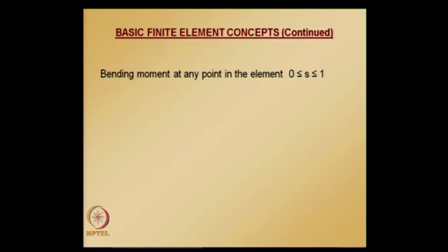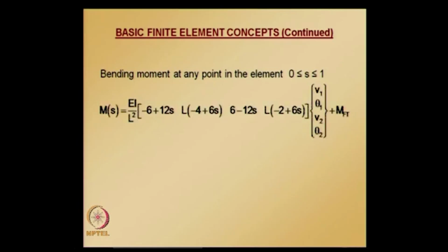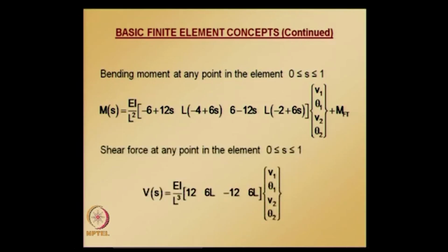And the bending moment at any point in the element is, as usual, the solution obtained by finite element by interpolating using finite element shape functions. To that the fixed end moment solution is added, and shear force at any point is given by this one, and here the fixed end correction is not appearing, because if you see the curvature expression, it is independent of s.